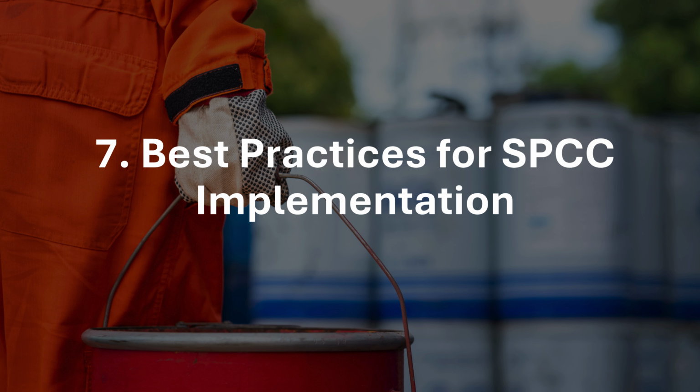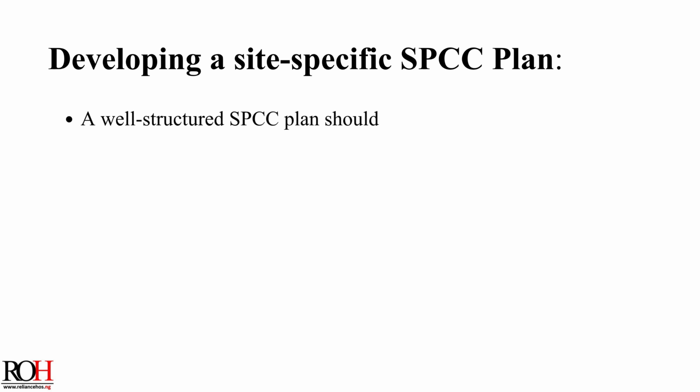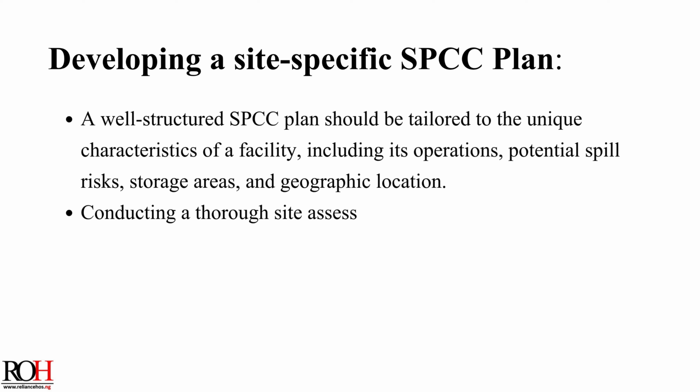Seven. Best practices for SPCC implementation. Developing a site-specific SPCC plan. A well-structured SPCC plan should be tailored to the unique characteristics of a facility, including its operations, potential spill risks, storage areas, and geographic location.